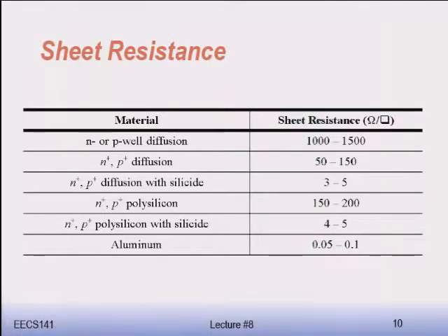diffusion is also the same level, N plus, P plus poly, and then light diffusion is low. So keep in mind that both this layer and this layer, if you are doing analog design, you will use to make resistors. Whereas typically a wire you don't use to make resistors because you need a wire that is very long to make a decent resistor, like 1 kilo ohm, right? So this gives you the idea that these layers are actually not very good conductors. Okay.